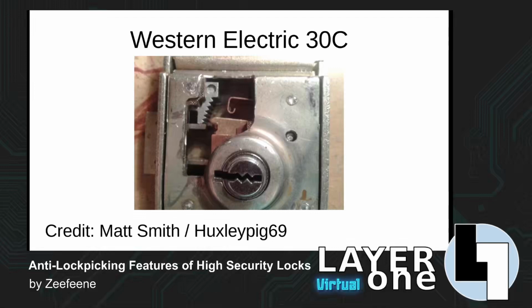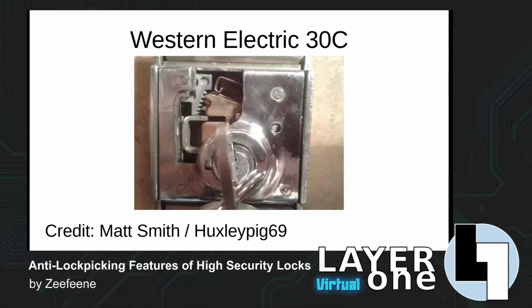and the way that it works is we have a bolt stump that needs to come across and test the levers, and we can move the levers as freely as we like, but when we apply tension before the bolt stump can come across, this serrated lever grabber interacts with the points on the tips of the levers and immobilizes them. So here we can see the gate on the levers, and we can see the stump trying to enter that, but we can also see the lever grabber has already grabbed all of those levers.